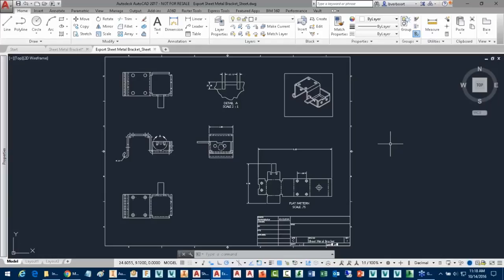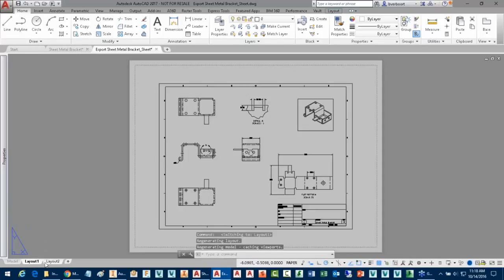And the receiver that might be utilizing the information in AutoCAD can kind of take control of their own destiny and get this drawing exported on their own. So you don't necessarily have to take that burden on in engineering with the Inventor to accomplish this task. You can just make your users aware, the consumers aware of the fact they can do their own thing if they'd like, either per view or the entire set of layouts in the sheet environment. So you'll see here now I have layout 1 and layout 2.